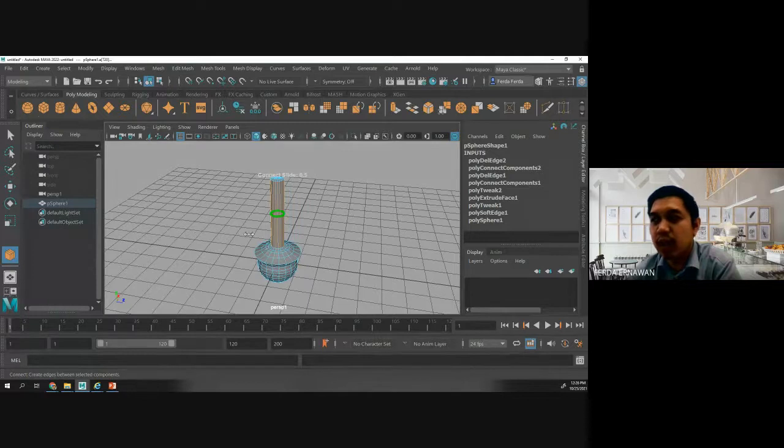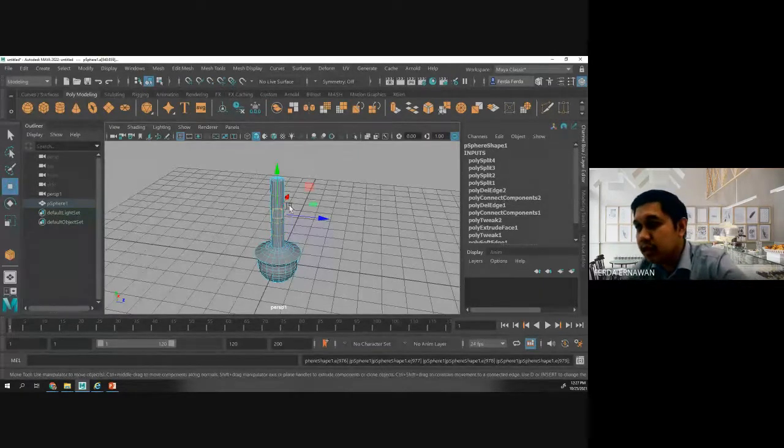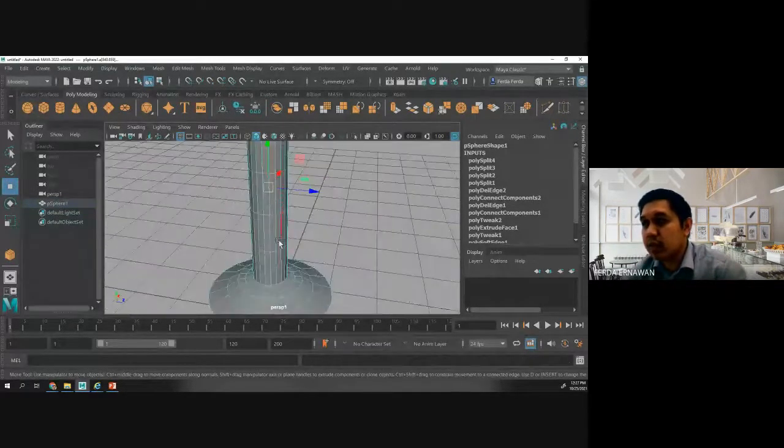Go to the right, it becomes more segments. You can see connect slide. So let's say I want to create 4 like this. Connect segment 4 means I try to make subdivision 4. 1, 2, 3, 4. After that, enter it. You can see I created it just now.